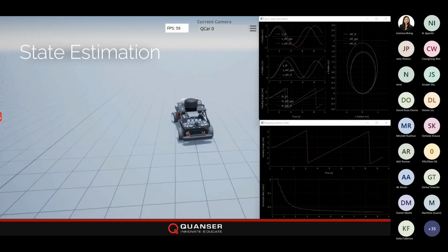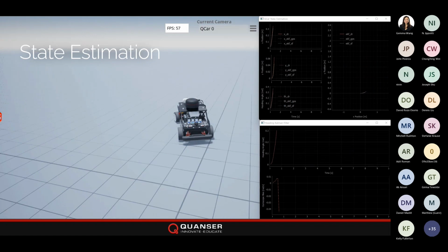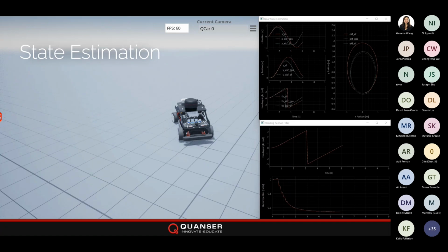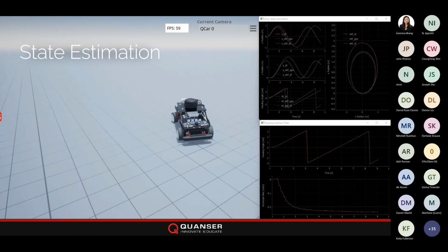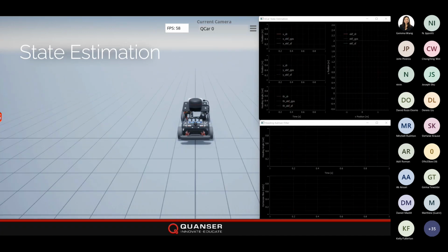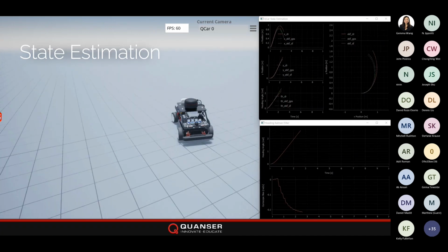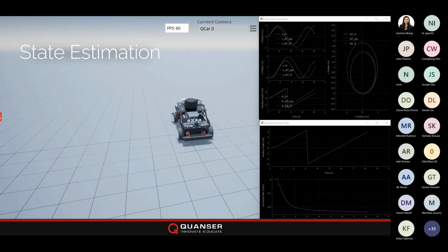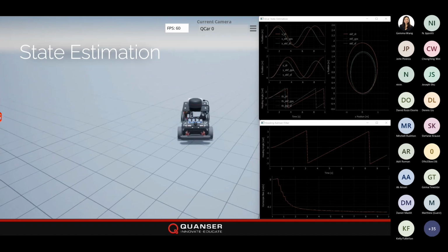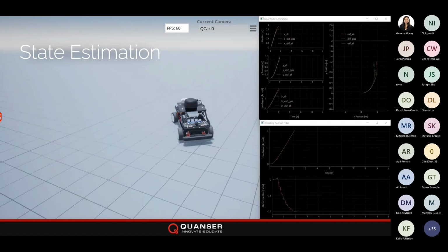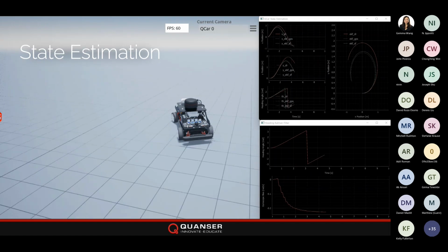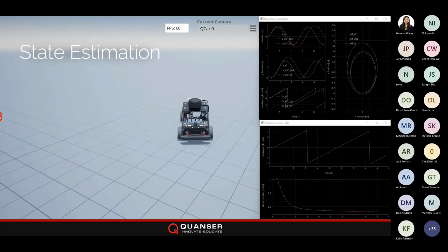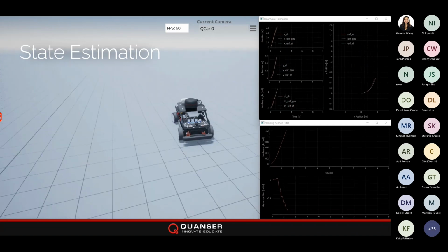In this activity, the focus is on estimating the state of the car, where it is in space. So the position in 2D space, as well as the heading angle. We look at a few different algorithms here to do it, of increasing complexity. The first, which in the graph you can see is the red, is just dead reckoning. We use a kinematic bicycle model, but if we just look at the encoder and integrate, eventually it accumulates errors with time, because wheels slip and other things like this, so it's not a perfect model. And so we need to use more sensor information to correct the deviations and errors. And so we created the next step.